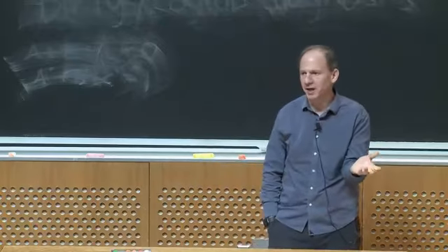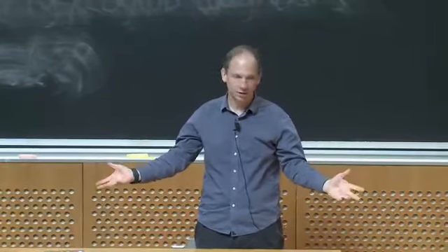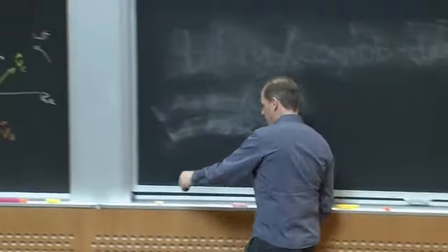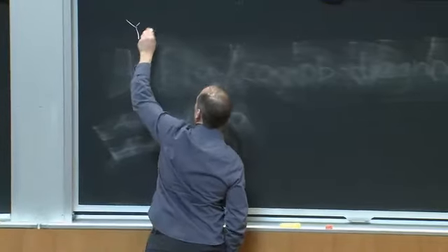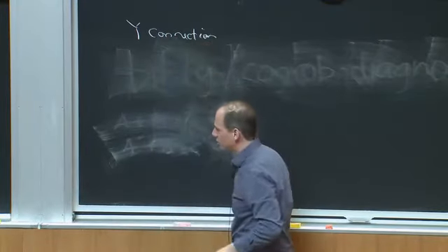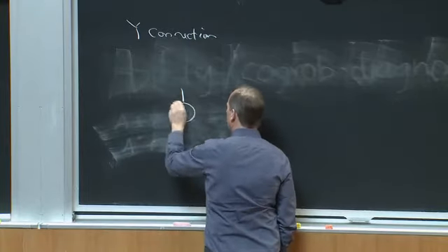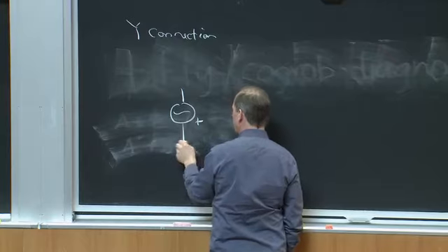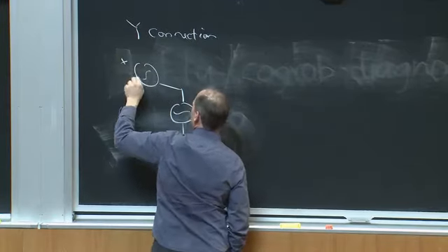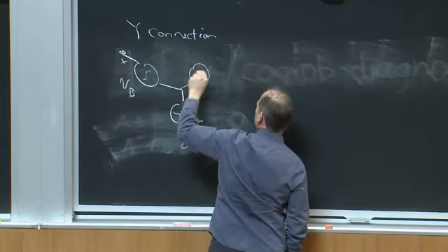There are different ways we might connect these 3 voltage sources. So suppose I create 3 voltage sources this way. The most typical way you see a source connected is in a so-called Y connection, also historically sometimes called a star connection, and one might do that this way. Maybe I would have VA, VB of t, and VC of t.